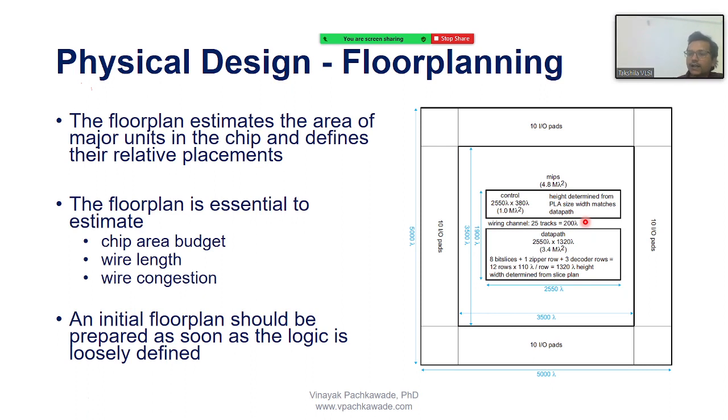Similarly, you can look at the chip from the top level, or you can see the cross section also, as I have explained to you. So metal 1 to metal 6, if you have 6 layers of metals, you can use each metal for routing many millions of blocks, automatically and in some custom way, to avoid the traffic congestion, because that is what is required in the chip.